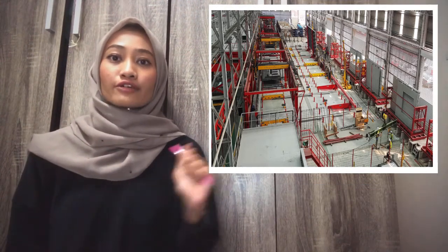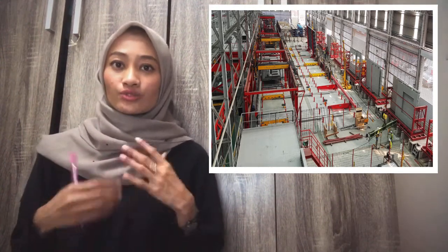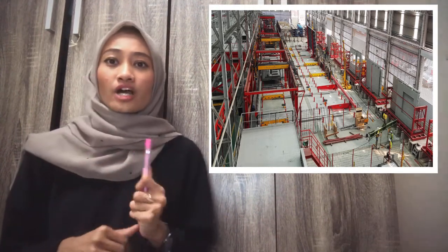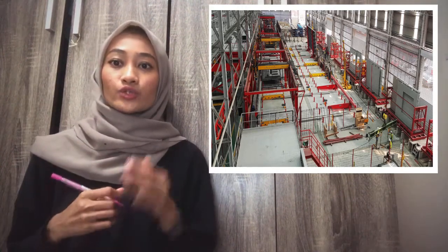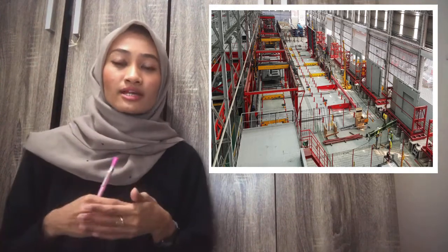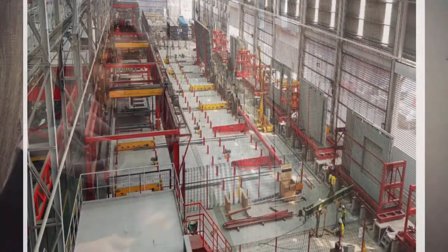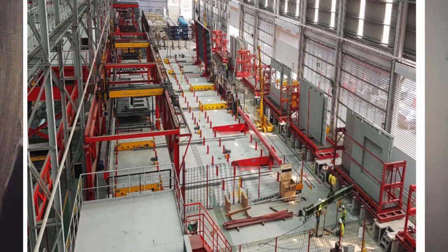The finished precast components are stacked on clean batons or plastic pads positioned to suit the design of the component. Care is taken to keep the stacks vertical and to ensure the batons are placed directly above one another within the stack. As we can see from the figure, this is the process of storage of high quality units in the works area. And next, we move to transport to site.